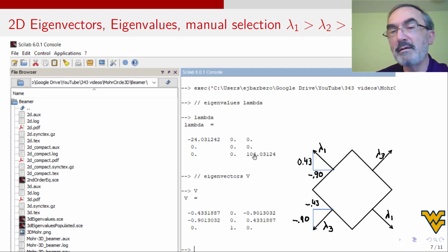Now, if you want the angle, like we did with Mohr's circle, it's easy. You take this number, use the tangent, you get the angle, correct? By the way, the angle is not at scale here because my sketching software doesn't give me much flexibility, but you know what I'm saying. You use this and the tangent to get this angle, and that angle will be theta p.